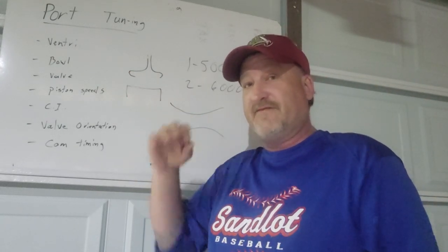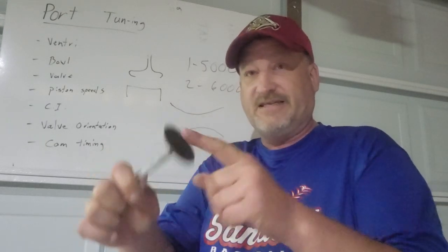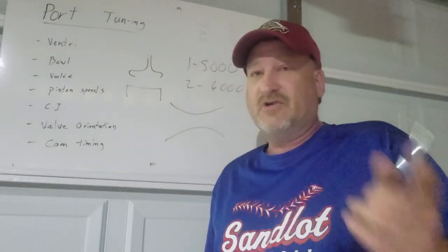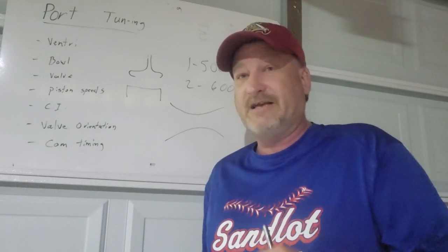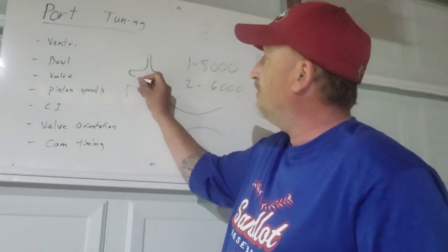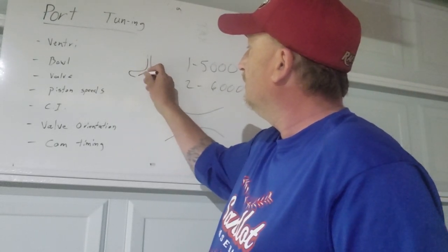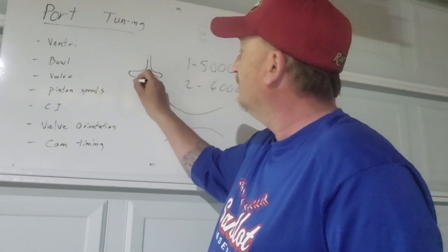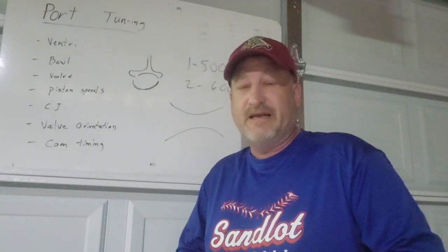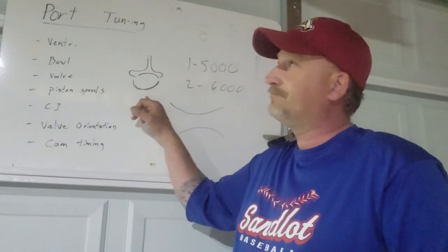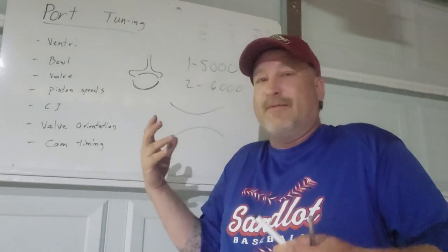Normally, all of your exhaust valves will still have this cupping orientation or design within the valve, because the air is only moving in one direction, basically in the intake, over the intake valve. And by having those pressures built up in the cup, it creates a pressure zone that is spherical. So again, the pressure becomes kind of like a mechanical device.